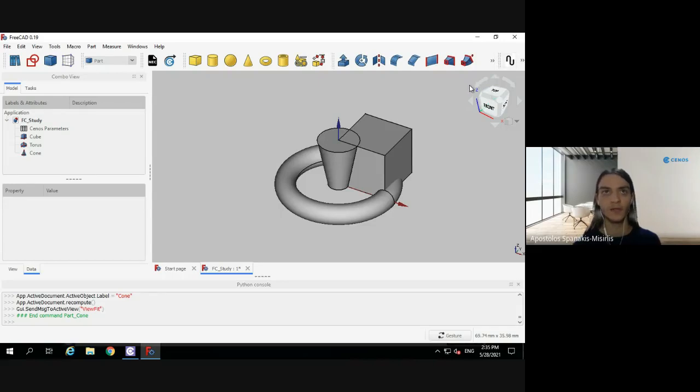This allows you to create all sorts of geometries, even if they are somewhat complex, which is common in various antennas nowadays. This encourages high precision modeling and ultimately the most accurate results for your antenna. So you can model your antenna exactly as you need it. Additionally, CENOS offers some RF engineering related tools for geometry modeling, such as feed network generation, PCB flattening tools, and others, which enable rapid prototyping of a variety of antenna models.